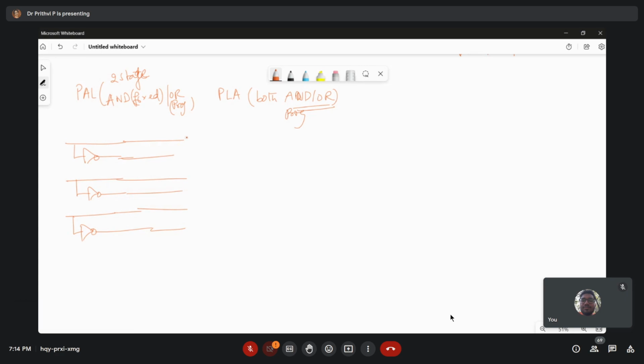Based on these inputs we are having, every term will be taken to your AND gate, something like this, having all terms in every possible product format. Okay, product terms will be readily available for us. How many are possible will be there as AND logic. Now this is fixed for us, and there will be an OR operation.